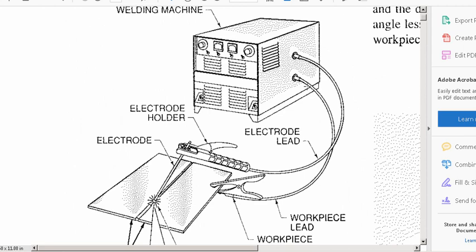You've got your welding machine, obviously, and you've got your lead that goes to your electrode holder. And keep in mind, your electrode is not the holder, even though I say it sometimes. Your actual electrode is your consumable right here. Your holder, which holds the electrode, is attached to your wire that's running back in. Then, of course, you've got your other wire coming out, which connects to your workpiece, which is your piece of steel, whatever you're using, and it's got a clamp to create that grounding.